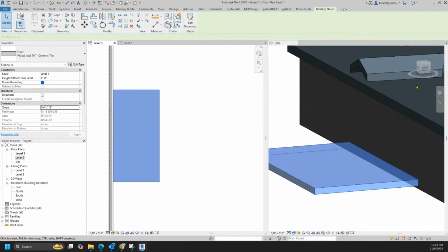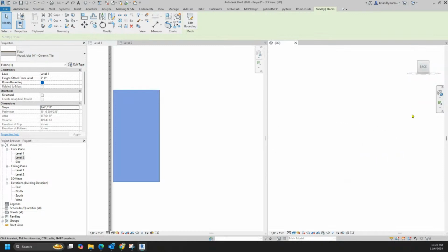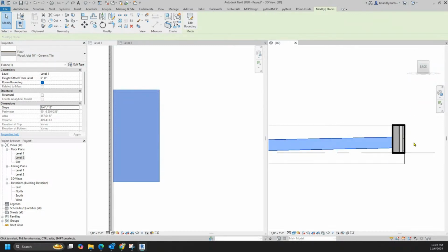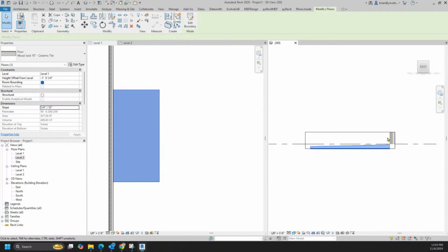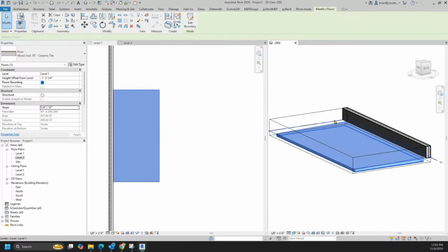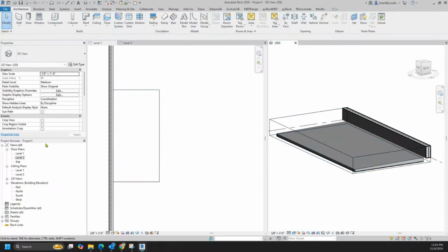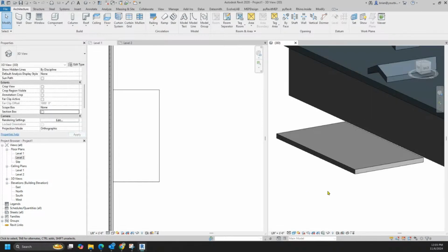Now, I would then look at it in this direction, and it would probably start about 2 inches below. That's how that deck actually gets built. Okay. Right? Right. But I'm not expecting you to build that exactly that way. I wanted to show you where your slope arrow was. But the bigger picture is any slab next to a building, you would always want to make sure you're getting that water away from the building and not into the building.